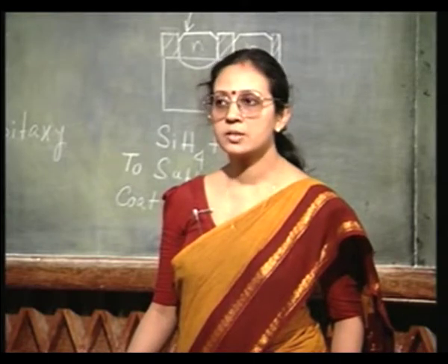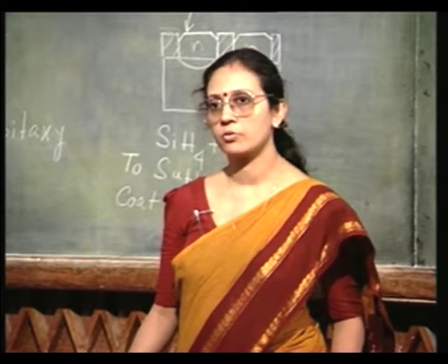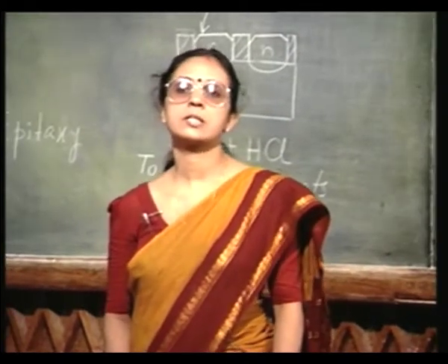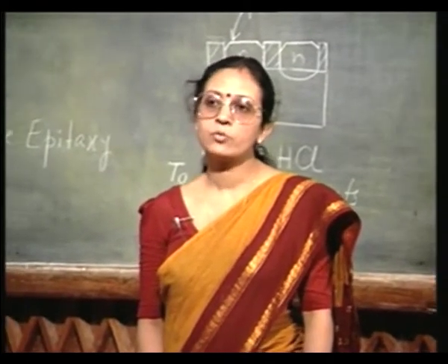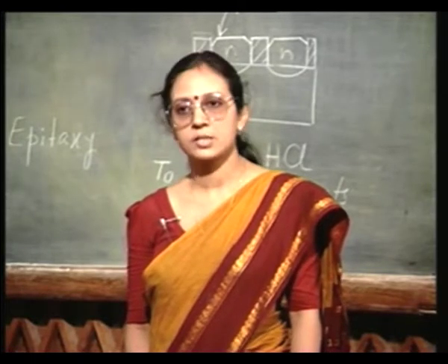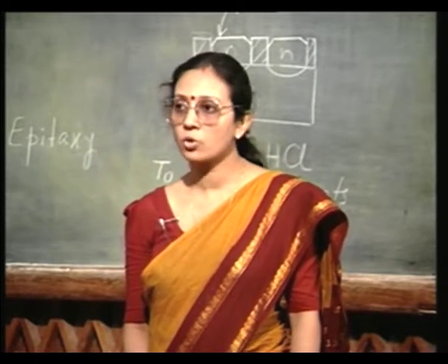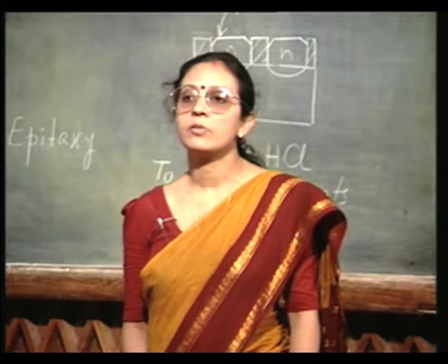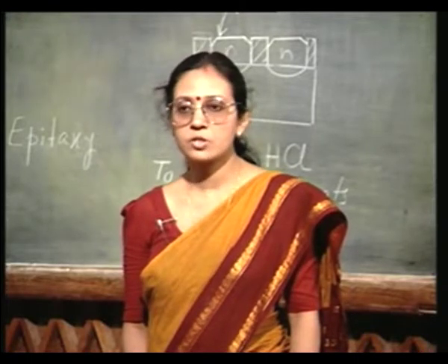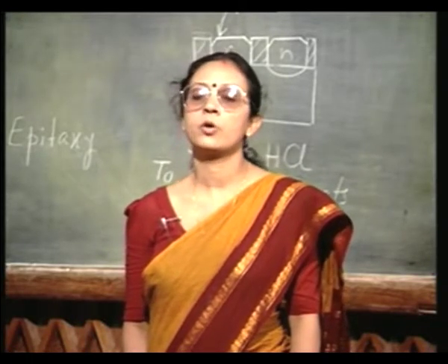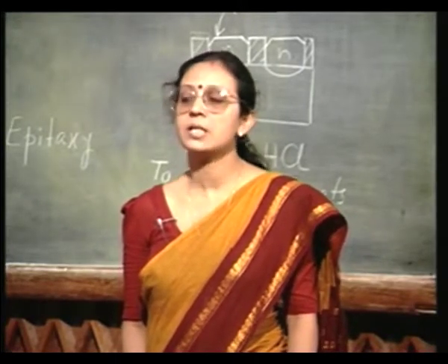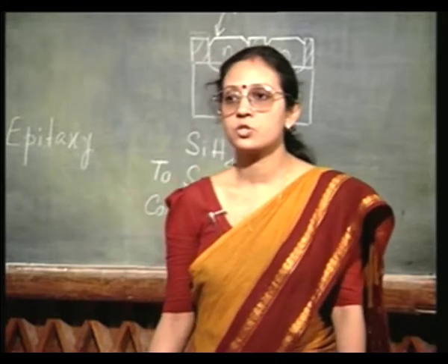Both of them incidentally use the same sort of philosophy, I would say, that you etch certain regions in silicon and then you fill that etched region. In LOCOS technique, you fill that region by growing oxide. Because the oxide is being grown, there will be a little bit of encroachment on either side, which is the bird's beak problem. In case of trench isolation, however, since you are filling it by polysilicon deposition, there is no question of any encroachment. But obviously, in trench isolation, your control has to be very high.